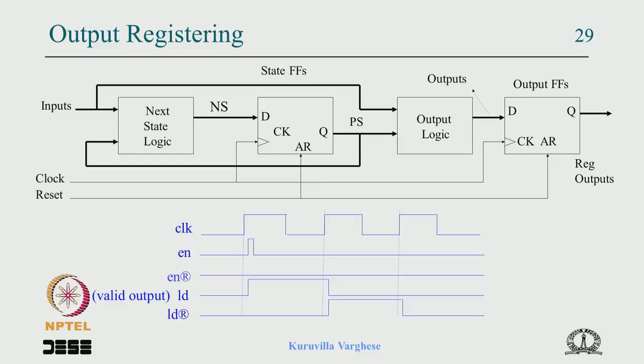You know that in the state diagram we come to the starting state, when it starts iterating or initializing, everything is delayed by 1 clock period. As far as this particular output is concerned, not a very serious problem, but you should keep that in mind. There can be side effects if you don't remember that, and a little care has to be taken with respect to